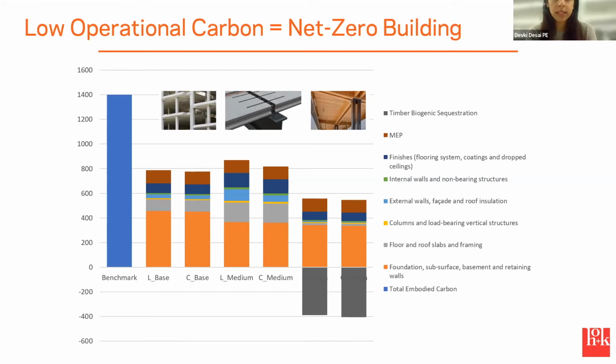We have our base scheme, which is reinforced concrete. We had one scheme which was proposed as possibly better, which was steel and then precast deck. And then a third scheme, which we were anticipating would come out ahead, was the mass timber option, which still had some concrete columns, though we couldn't do mass timber columns all the way down due to limited strength.